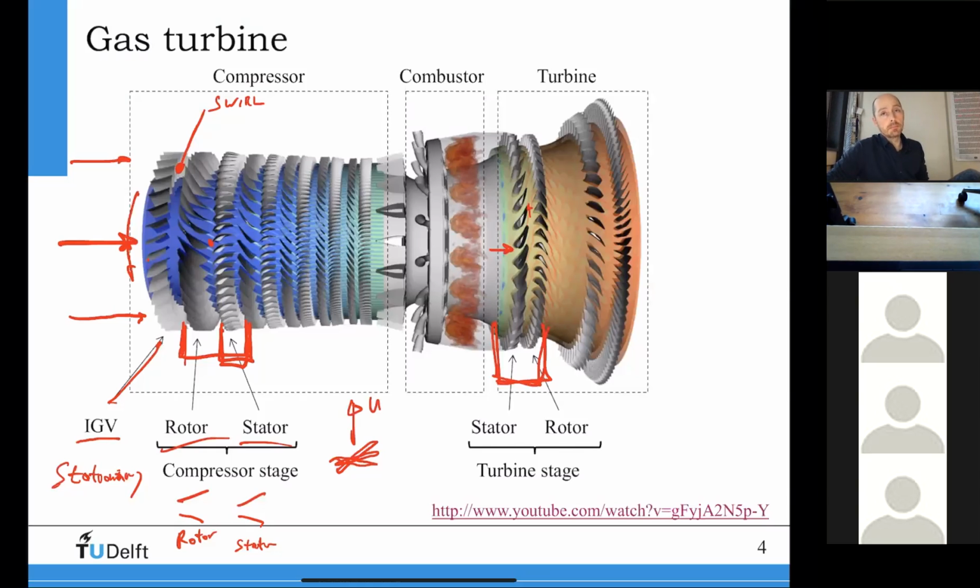Of course, the highest efficiency is probably going to be at the design condition of 100% at full load. But if you go to part load, the efficiency significantly drops. But there are also several possibilities to keep the efficiency at part load still high. There's also research being done right now on these topics. And I think Sike has mentioned this also. So a lot of gas turbines nowadays are used as peak shavers, right? You need to provide a lot more electricity for a certain amount of time, so you turn on the gas turbine to provide that amount of electricity.